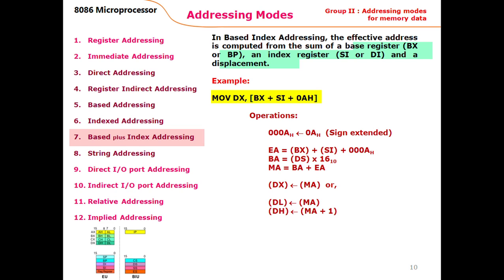If it were an instruction, then it would be the code segment, but here data is being accessed, so the segment register will obviously be the data segment register. The content of the data segment register is multiplied by 16 in decimal, or left shifted by one hexadecimal digit, and this gives us the base address, just like we did in the example in the previous slides. The effective address and the base address are added to give the memory physical address.